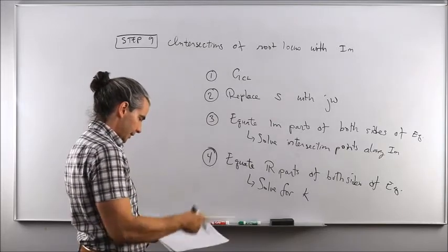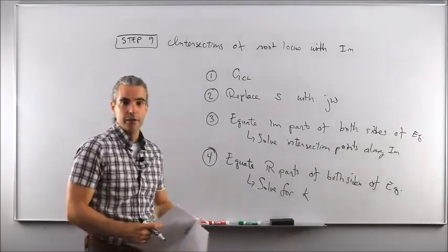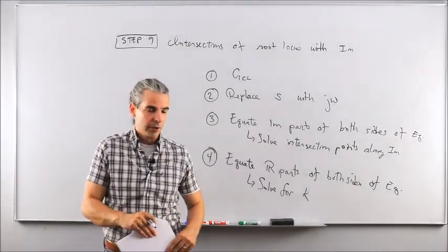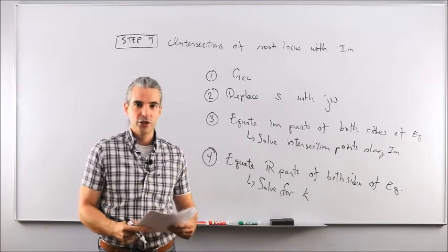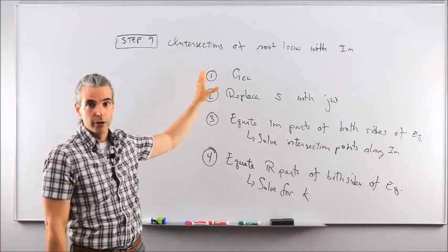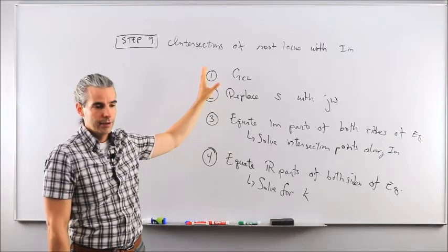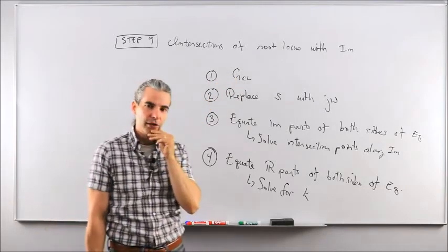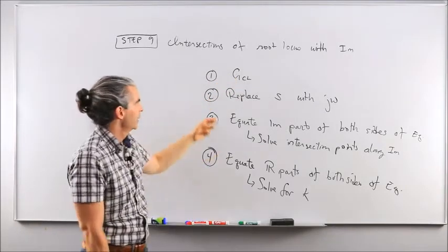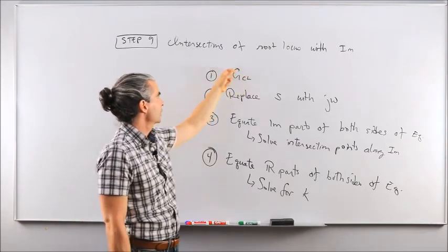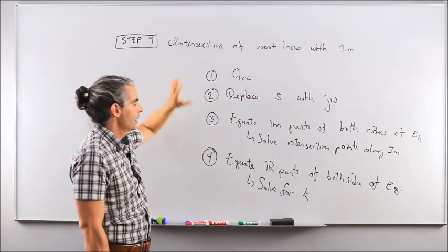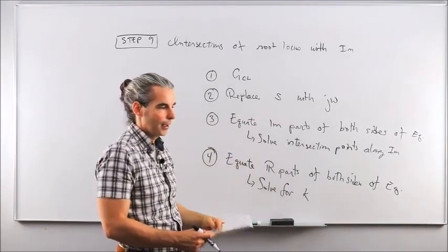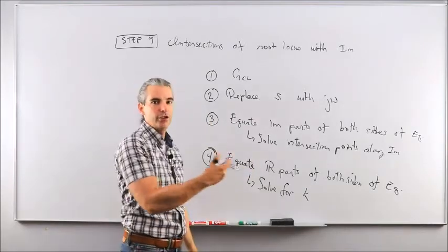And that's all there is. Okay? So this is really a recipe. There's not much thinking involved. Just make sure you follow the step-by-step procedure as outlined on the whiteboard today. And be cautious about what transfer function you're using for each single step. And again, you only use the closed-loop transfer function in the final step. Otherwise, everything is based on the open-loop transfer function. And I would highly recommend that you draw the root locus as you go along.